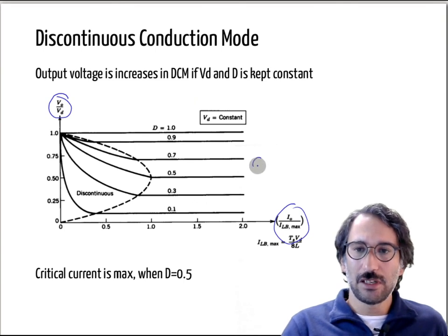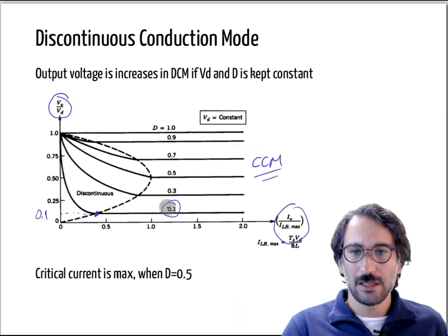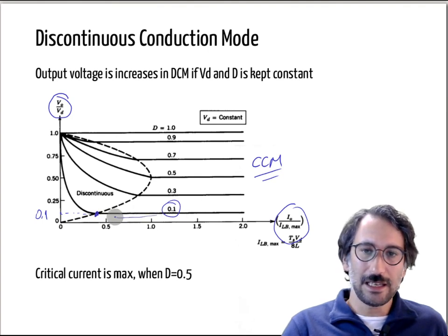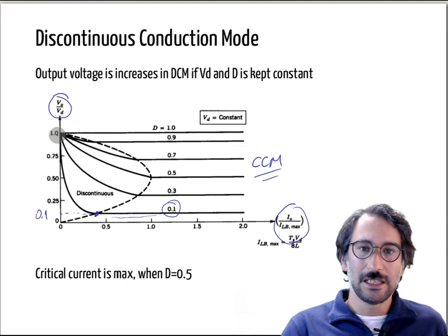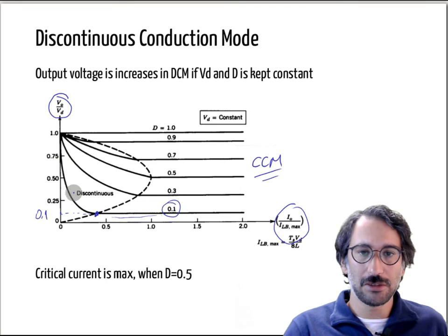Again, if you are operating at CCM, and let's say your duty cycle is at 0.1, so your ratio is also 0.1. Right, but that is valid for CCM. Okay, and actually if you just get into the discontinuous conduction mode, this is not a linear relation anymore, so it just starts climbing up and up. So you can derive it yourselves as well, but the derivations are available in the textbook. I don't want to get into detail of that characteristics.